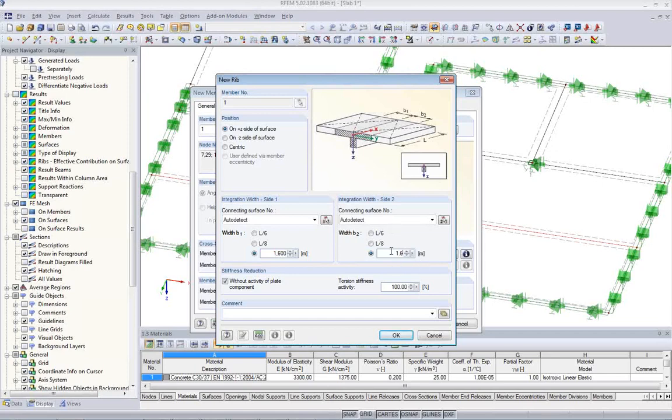So the software will then integrate the internal forces in the slab into 1D member internal forces together with the beam, the eccentric beam that is located below the slab. We will see the forces then later as beam forces. And we will also design this T-shape in the member design of our concrete members.